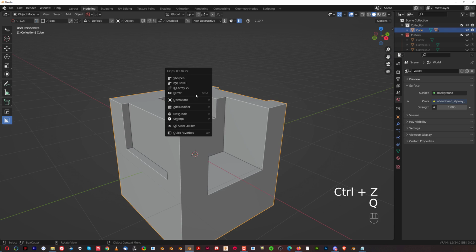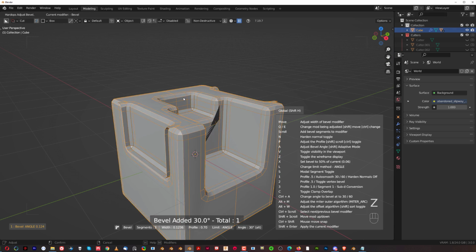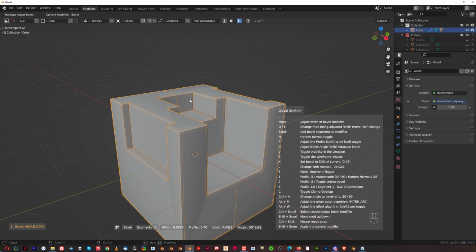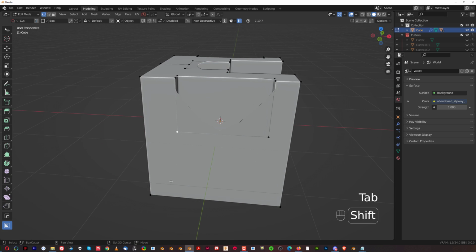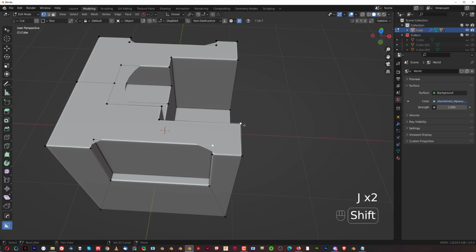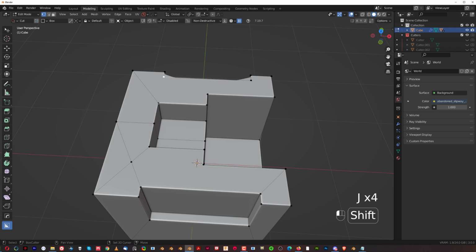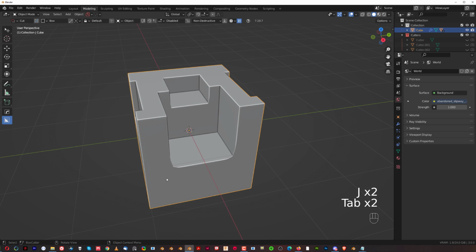But if you go to Bevel, and you press Z for wireframe, and you scroll your mouse down to 3 segments, press P, and move your mouse to flex this, and then press A to adjust the size of it, you can adjust the parameter loops on the entire mesh, and then Control 3, and you're almost there. All you need to do is simply connect these edges that are not quads, and create other quads or just simply smaller ngons that are going to help you with the shading on that mesh. All right, doesn't have to be perfect quads, it's going to work, guys. So there you go, really easy, no effort, and boom, there's my subdivided mesh.